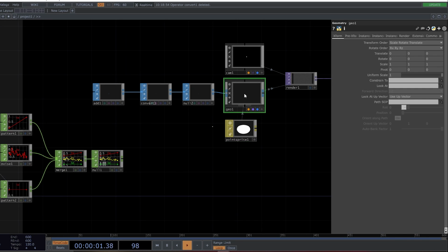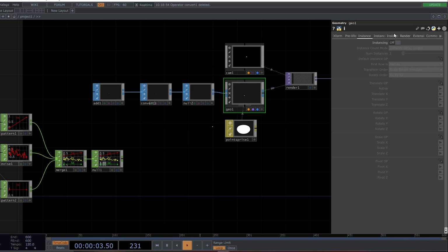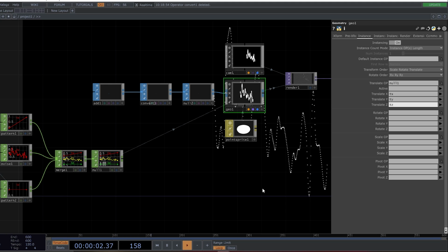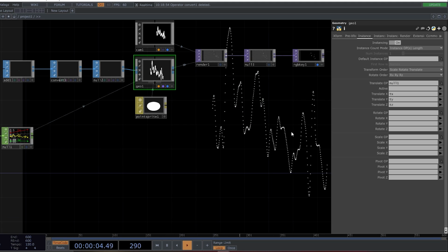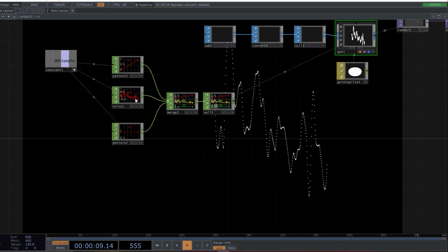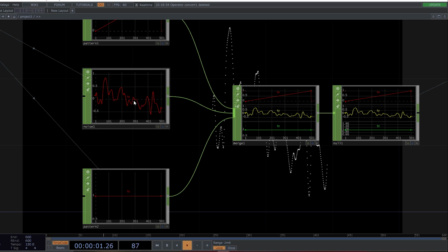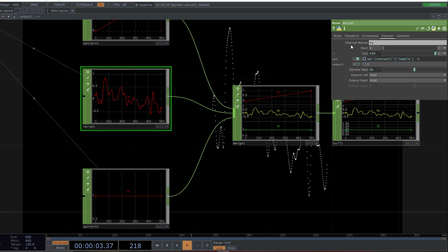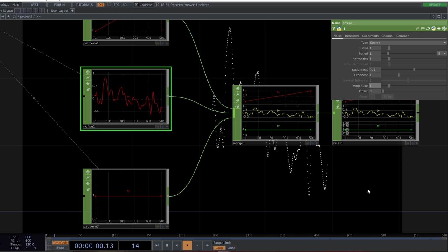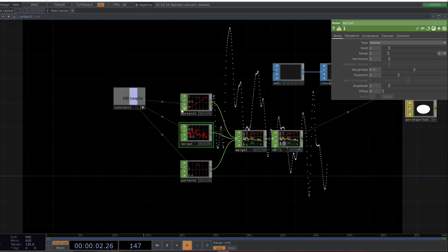Now is the time to go around and use the instancing. Let's enable the instancing. I'll be using null1 to have my instancing defined, tx, ty, and tz. As you can see, the whole pattern is nothing but the replication of the waveform that I see on my noise. As in when I change things on my noise, it's going to change its position on my render network.